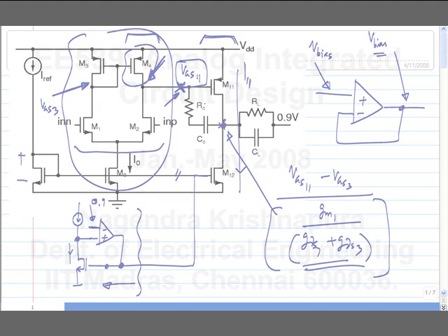So my argument was that instead of using a simple stage, we use a cascoded telescopic one. We anyway don't need any swing at the output of the first stage. That depends only on the second stage gain, right? If we do this, then we would have to care about a lot of systematic offset that will come. Yeah, that's true. So you can try and design that. You can design a telescopic cascode for the first stage. That's what you're saying, right? Yeah, that's correct.